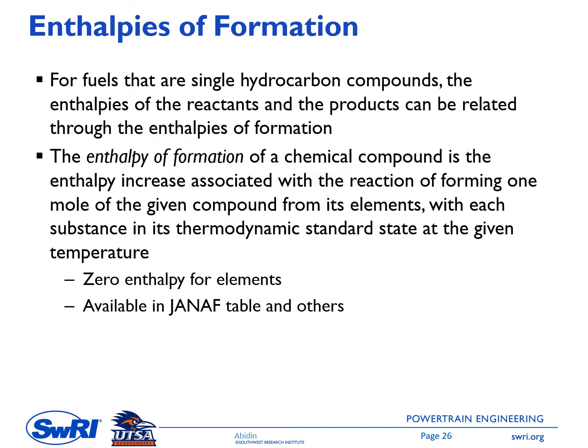Next is enthalpies of formation. This parameter was introduced to solve the problem of the enthalpy or internal energy datum for a reacting mixture. For fuels that are single hydrocarbon compounds, the enthalpy of the reactants and the products can be related through the enthalpy of formation.